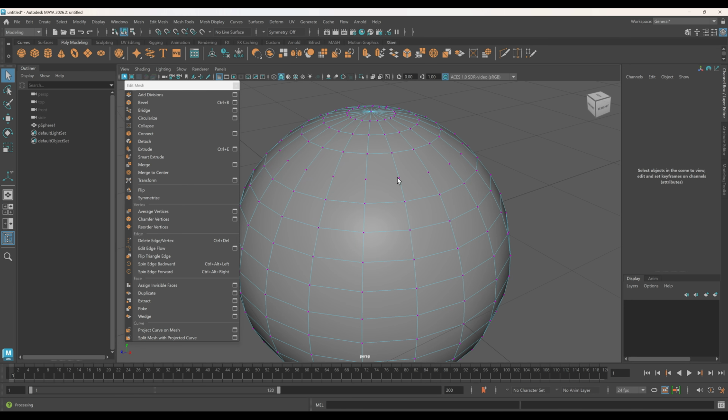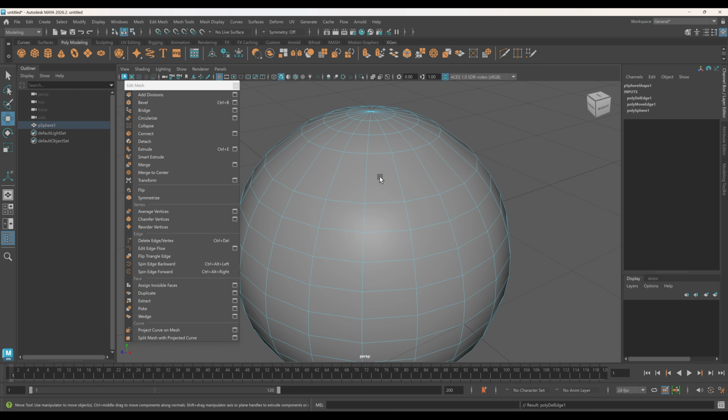Not only Maya, but most 3D polygon modeling applications are designed around triangle and quad topology. Even if a face appears to be a quad, leftover vertices can turn it into an n-gon. For this reason, it is recommended to use Ctrl-Delete so that both the edge and the associated vertices are removed.